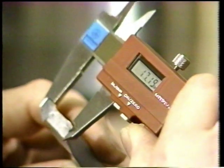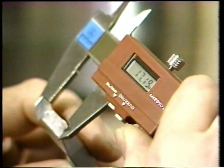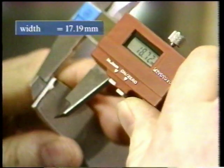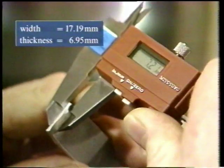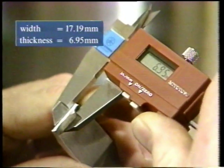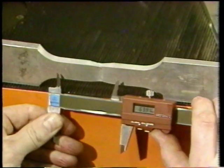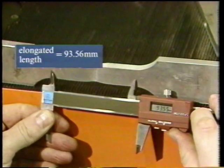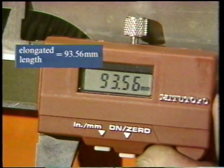Right, well, that's the specimen broken. Now let's measure the reduction area and elongation values. Here's the width and the thickness. Now for the elongation. Remember, the punch marks were originally 80.0mm apart. If you refer to your video notes, you'll see what we want you to work out from this test.